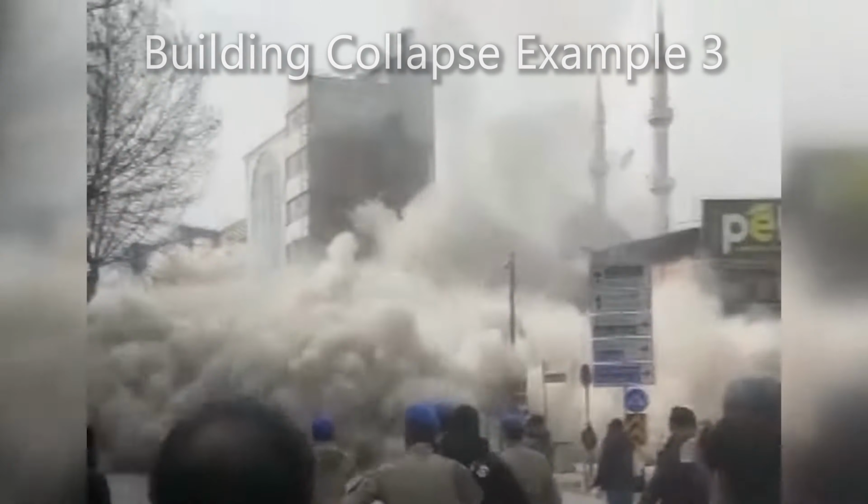In this final example clip, a structure damaged by the early earthquake sequence appears to suffer a bottom story failure along what looks like a storefront side. The bottom story appears to give way at the storefront edge, possibly causing it to lean towards that side and collapse. It is likely that the storefront side of the building had door and window openings, which may have made it laterally weaker or softer than the other sides of the building.